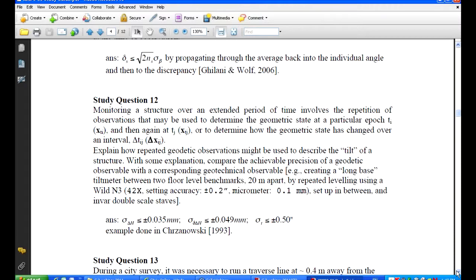And then you have a similar variation directly with the 0.2 arc seconds over the length of sight, which would give you a variation in the rod reading. And you take those two as variances, combine them, take the square root, and that gives you a variation in a single rod reading as a consequence of pointing and leveling error.